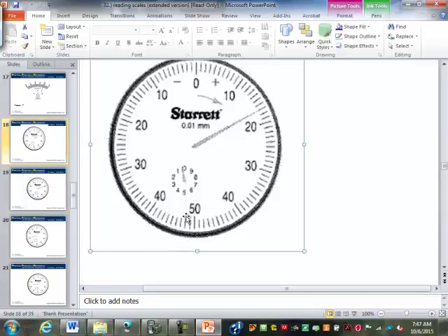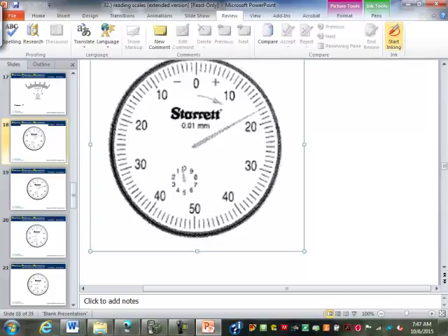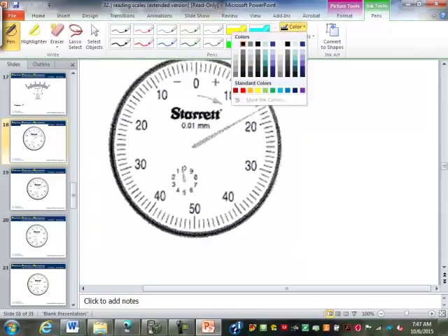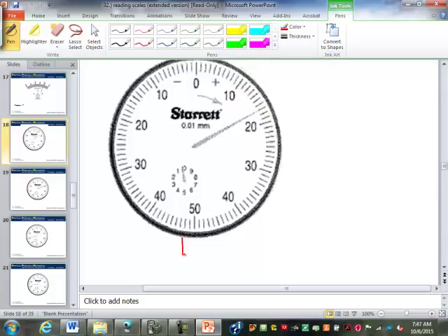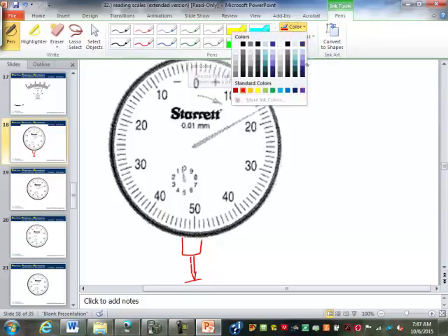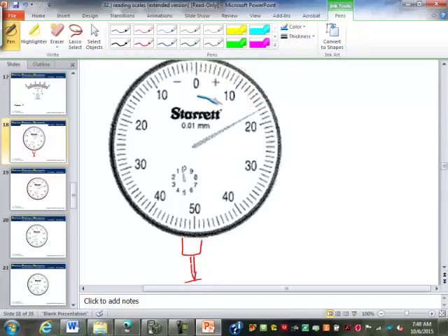Basically, this guy's just a little button. Generally, it's just a little button down here that sticks out, and that hits the surface, and it tells you in or out how far it is. These can read positive or negative, whether it's being pushed in or pulled out, or usually it springs out, so whether it's past its neutral point. Looking at this arrow is telling us that when we engage this, the needle went that direction, so that tells us we're going in the positive direction.